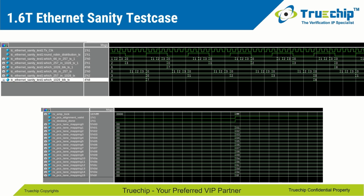Now, in the next slide, we can see two screenshots of the waveform. The first screenshot is from the transmitter PCS, where we can see four 66-bit blocks are collected to form a 257-bit block, and four 257-bit blocks are collected to form a 1028-bit block. As we have two instances of PCS, this process of collecting four 66-bit blocks and encoding them happens in a round-robin fashion. Here, it is governed by the round-robin distribution TX signal.